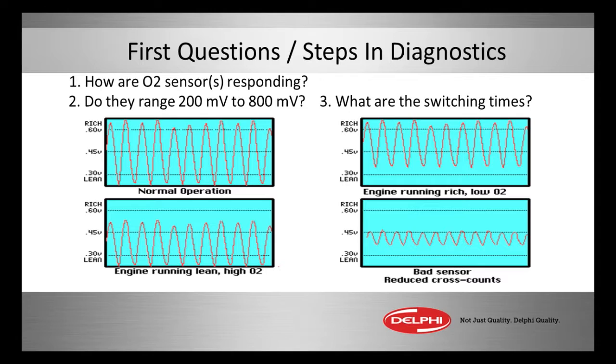But if we see over in the lower left-hand corner an O2 sensor is biased lower, it doesn't really get much over the 450 millivolts of bias voltage provided by some PCMs to the sensor. It mainly hangs out below that. So that's indicating we're running lean. So we have a higher air-fuel ratio, actually a lean ratio above 14.7 to 1.